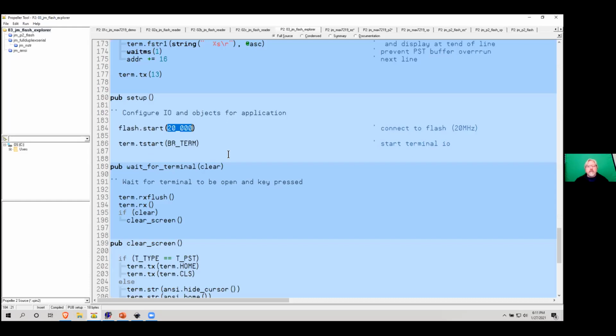When you turned on the laser tag weapon, there are buttons on the weapon for selecting things in the display. By holding different buttons down, every application knew to look at those buttons on power up, and it could read the file off of the SD card, put it into the EEPROM, because writing to an EEPROM is pretty easy, and then it would reboot and you would have that application.